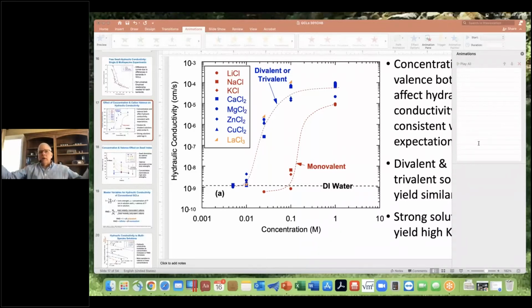But when we get in that extreme range, then we're usually getting to a bentonite-polymer composite GCL. For example, in the highly alkaline range, we frequently use bentonite-polymer composite GCLs for bauxite liquor. Bauxite liquor tends to have a pH between about 12 and 14, really alkaline stuff, because they use sodium hydroxide to dissolve alumina. So there are commercially available bentonite polymer composites that work with those hyperalkaline conditions. Same thing with the highly acidic conditions as well. A bentonite polymer composite will work in that. You have to get the right polymer that's appropriate for an acid as well.